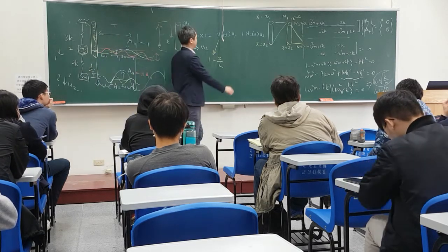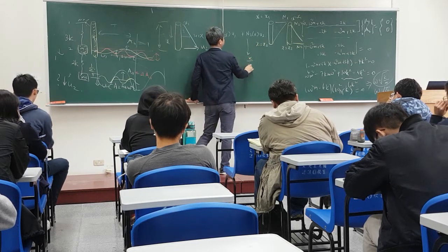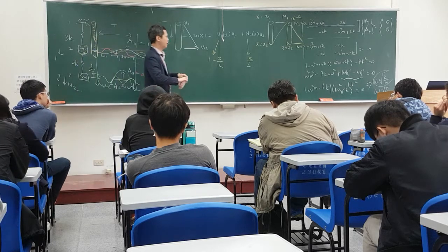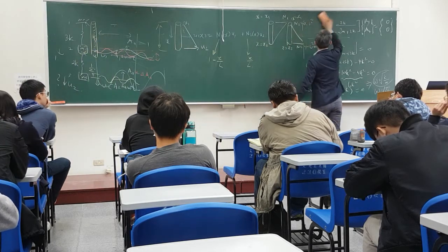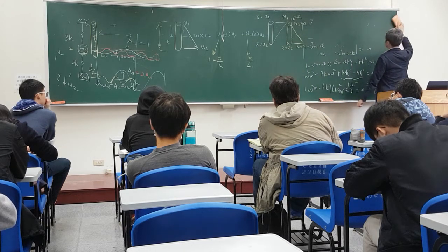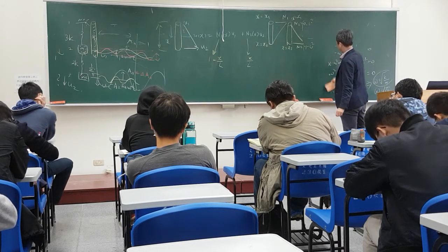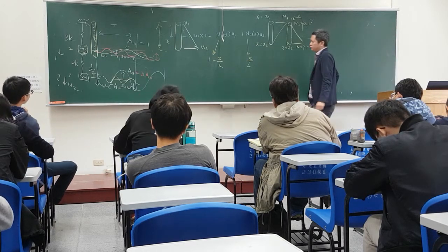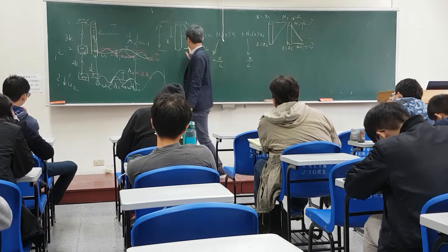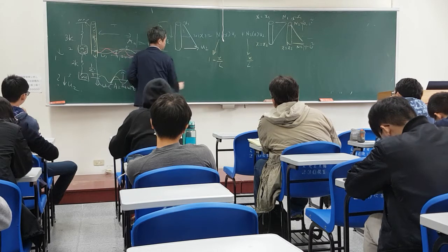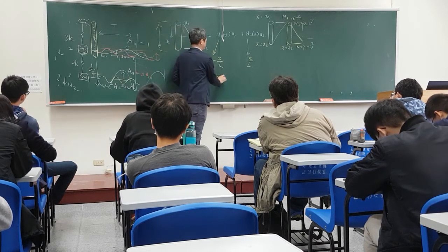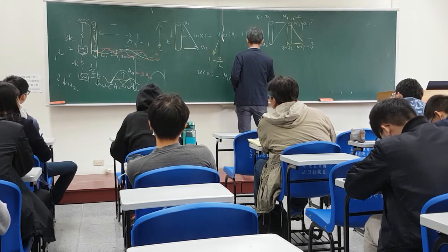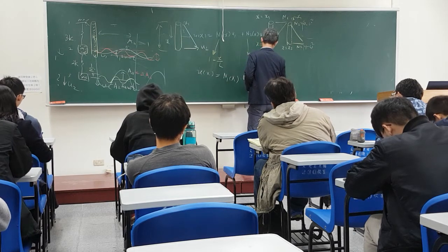And this one is x over L. This is what you have for your displacement. We're going to next find out the velocity, because we are assuming the profile won't change. So what you can now write is u dot of x equal to N1(x) times u1 dot plus N2(x) u2 dot.